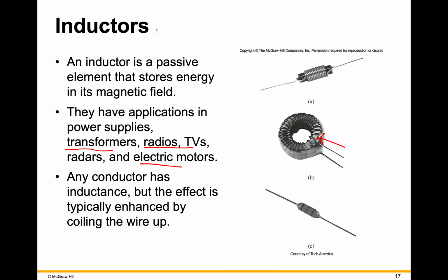So you double dV/dt, you'll double the current, and so on. Inductors, that's not the case. There's not a bunch of different kinds of materials that you can stick in here to get linear behavior of the inductor. In fact, the introduction of a magnetic material limits the range to a very narrow range, or a very small range, typically over which you'll get linear behavior.